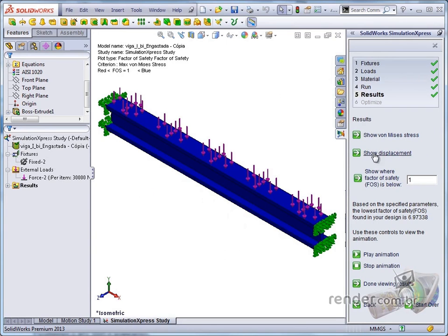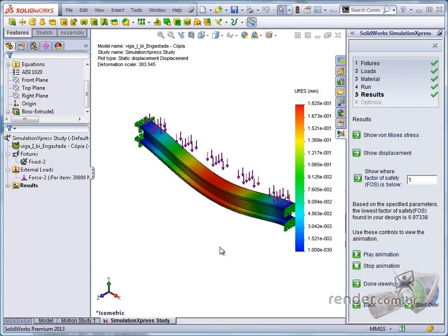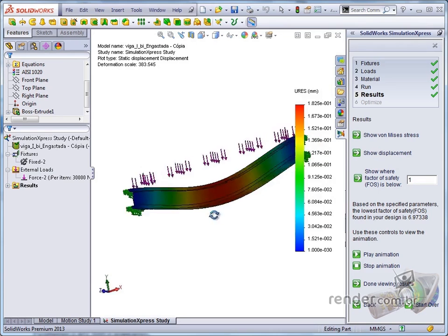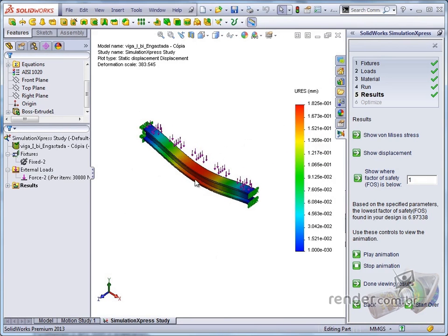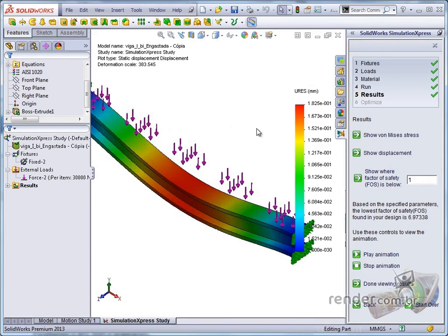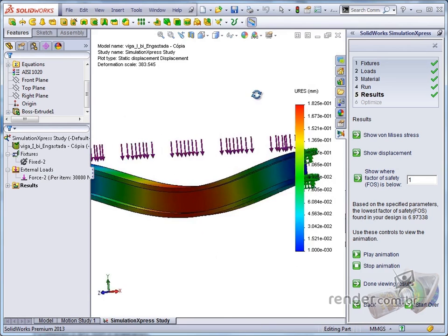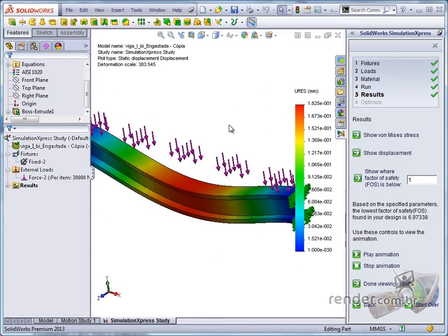See the deformation result and note that due to the fixation at both ends and the applied force, the beam tends to deflect. And the maximum value of this deflection occurs in the center of the beam. Therefore, when working with beams, it is very important to perform deflection calculations due to the applied efforts and restrictions.